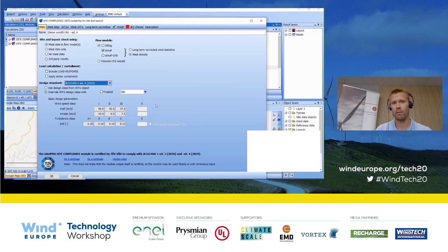Since this is edition 4, you can check the tropical option here to get the typhoon classes, and you can select the different design classes, which you saw in my presentation. So in this case, we will assess this class 3A, and I'll just step briefly through the setup tabs here and go to the IEC checks.